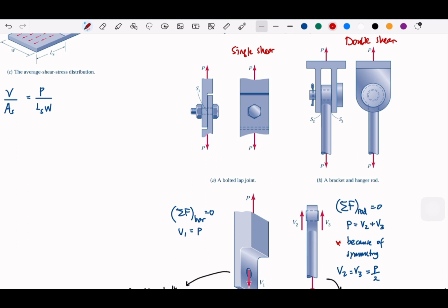If you see something like this, then you could immediately say, oh, that will be double shear. You will use the double shear formula. If you see something like this, only 2 layers, then you are going to use the single shear. Okay? And it will be given, either in the words or in the picture. You see the figure. So that's the direct shear, the single and double.